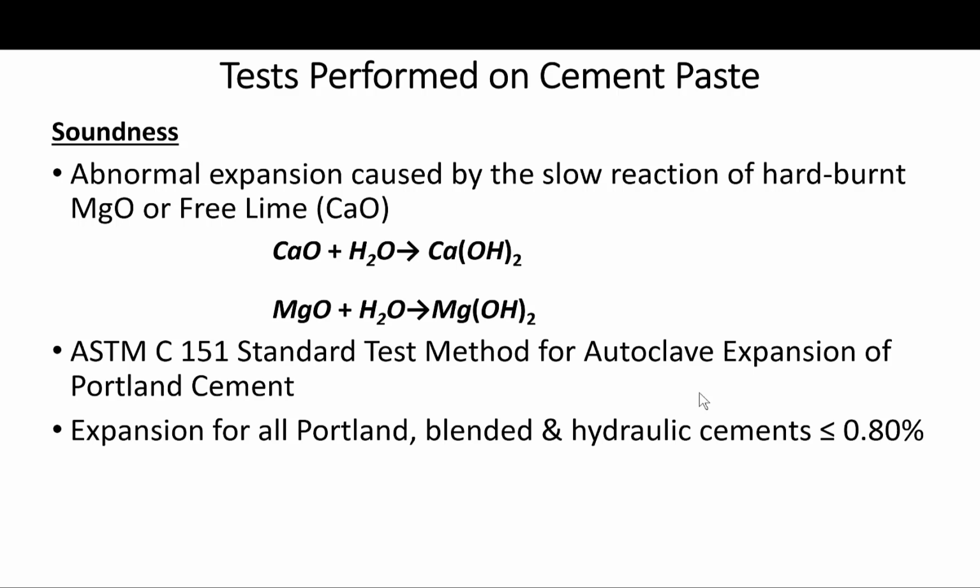Unsoundness in cement is caused by, as I mentioned before, the slow hydration of hard burnt magnesium oxide, MgO, or the free lime, uncombined calcium oxide, and by the reaction of gypsum with C3A. This will be discussed later.